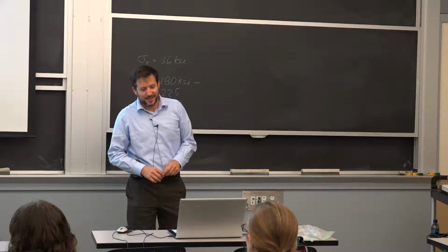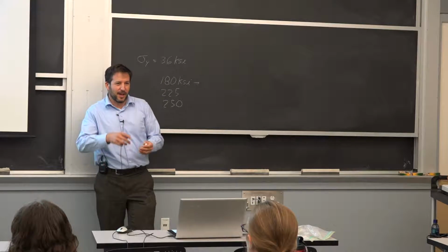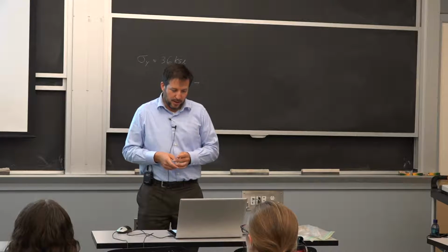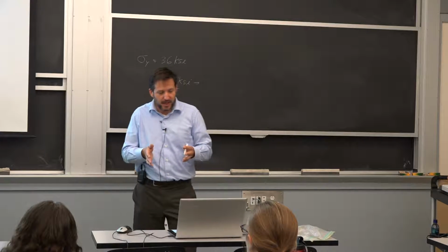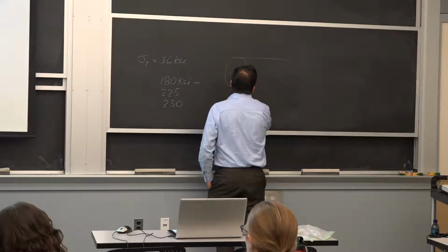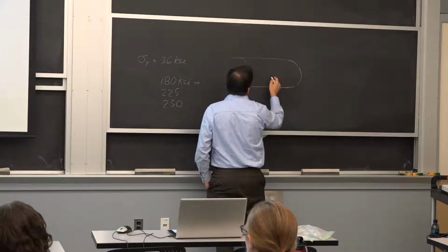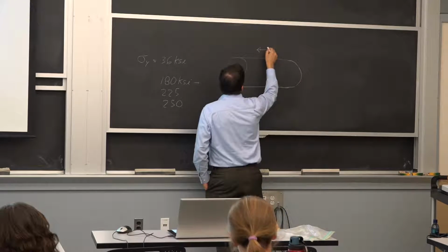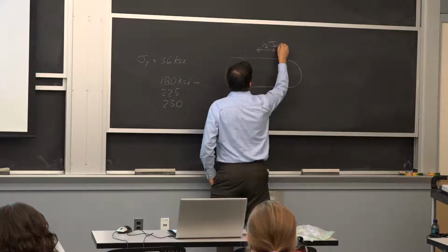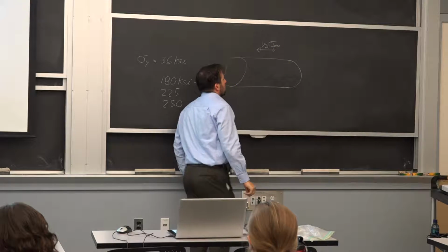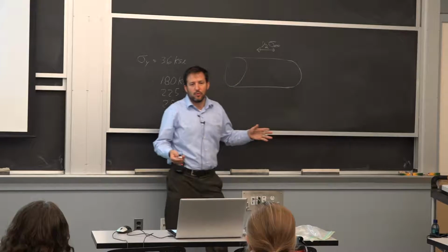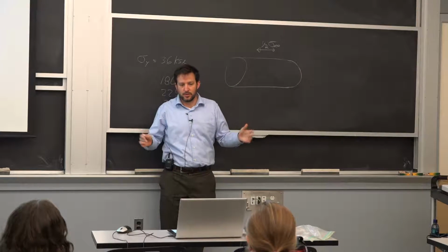Now, this is all nice, right? Because we're having all our wires essentially resisting the hoop stress. These cylinders don't really have tension. If you remember your basic mechanics, if you have a closed cylinder, you're going to have a stress this way that's only 1/2 of the hoop stress. If the ends of the cylinder are free to move, there's no tension. They can just go back and forth.